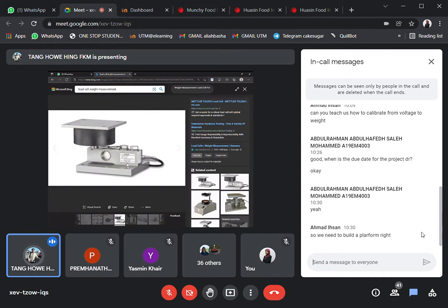Okay, you can see that this is also a load cell. So you are going to screw it to a plate, for example. And then later on, here is some form of an empty space, and therefore you have a place for you to hold that 1 kilogram of weight. So 1 kilogram of weight will be applied onto this side, and because this is screwed and fits to here, this load cell is now performing just like a beam.